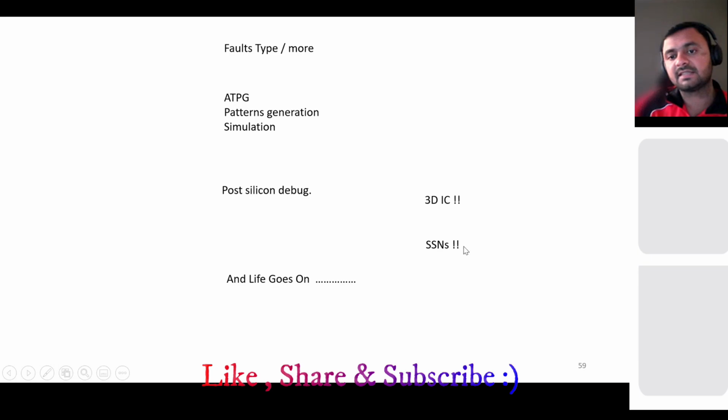And there are streaming scan networks. Industries are currently exploring these. Basically, how can we test a chip by using just a single in and single out. Suppose I have a single input and some internal logic, like the LPCT we saw, which generates all the internal logic, and through a single output we can just shift out and see the behavior, whether the comparison is correct or not. So this is how it happens.